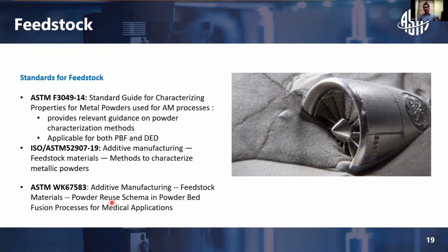So when you reuse the powder, again, you have to have some kind of mechanism in place to make sure that you have some check and control to make sure that the materials satisfy specifications all the time. So this particular standard helps you to create different powder reuse schemas, which can be applied for your specific application.